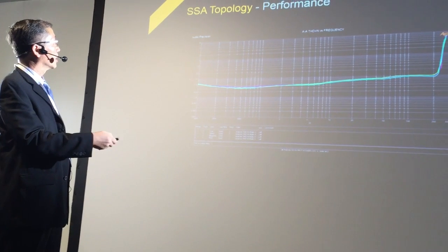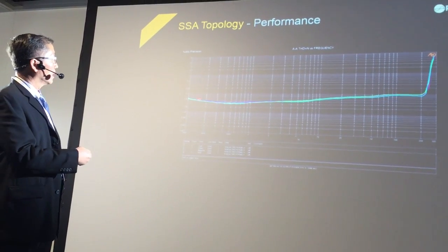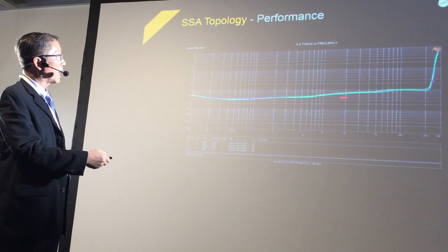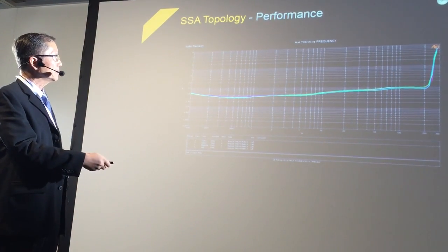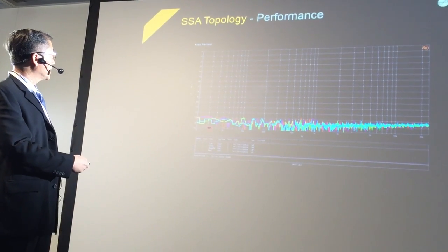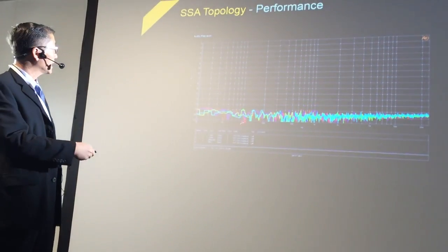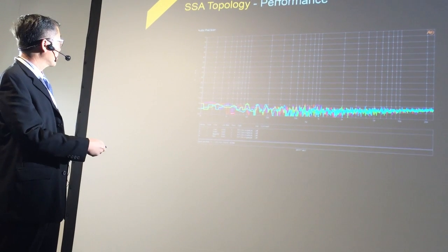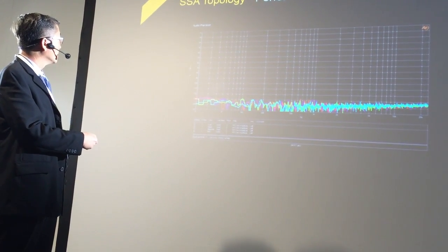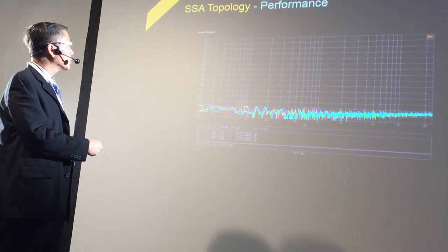So this is a curve of traditional distortion versus output power. You can see it's very consistent. Then we see the noise floor in a multi-channel amplifier. There's no strange noise. Everything is below, and there's no FFT peak above minus 130 dB.